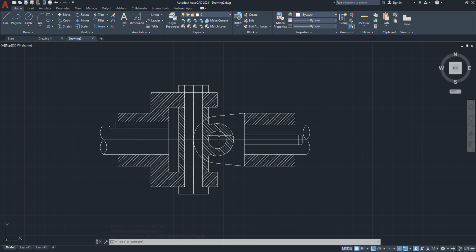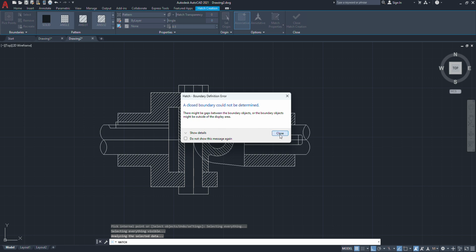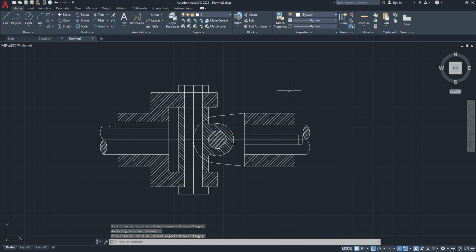Here you have the pin, so that we will hatch with a smaller, closer line spacing. So there we will give say 0.25 or 0.3, very close. Okay, and 0.3 this portion and this portion. Okay, and here also, and here also. So enter.